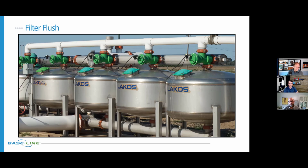Yeah. And Dan, there's a couple things that stand out here. Number one is that when you add automatic backflush to a filter system or a pump system, there's immediate cost that comes along with that. I've heard recently anywhere from $1,500 to $3,000 for auto backflush. Essentially that capability is built into the base station 3200. You just need the pressure transducers to read it. So you have that control out of the box with the irrigation control system.